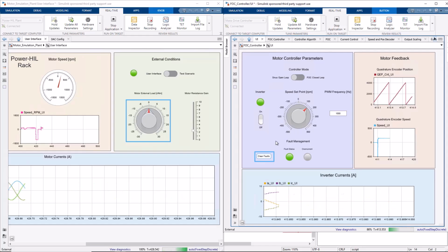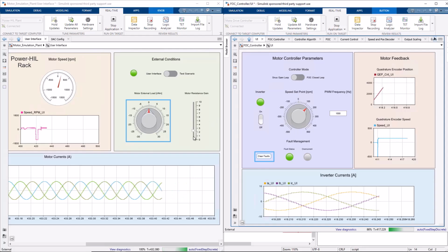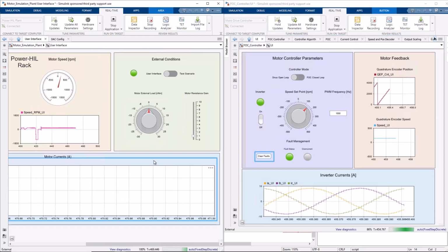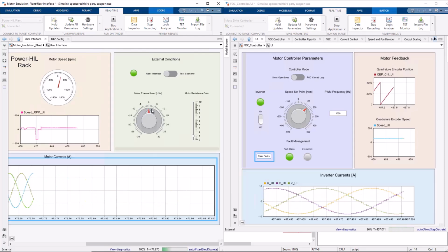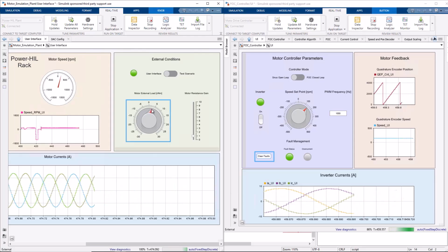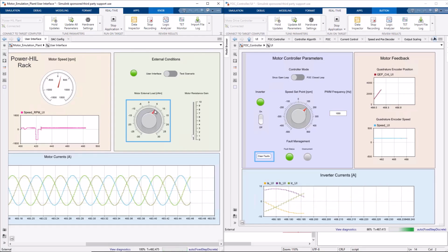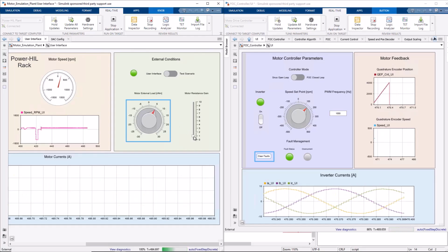One last interesting test is to increase the resistance alone in open loop. As the resistance increases, less current can flow in the coils, and the torque produced by the motor gradually decreases, up to the point where the load will make the motor spin backwards out of control. Interestingly, the resulting back EMF currents did not trigger any faults.